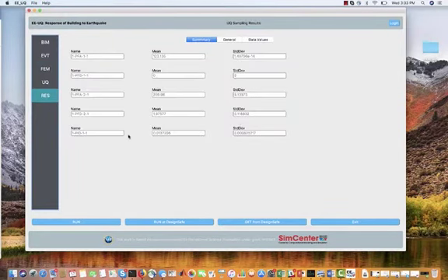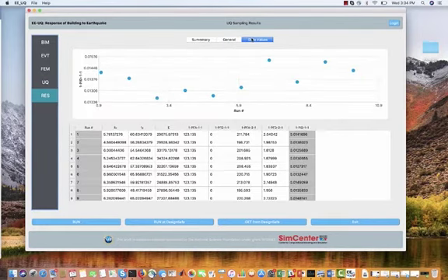And there are the results. For example, the interstory drift. For story 1 and 1 degree of freedom direction, we get the mean and the standard deviation. We can get the peak floor displacement at the second floor and the peak floor acceleration at the second floor in the 1 degree of freedom direction. We also can see this graphically.